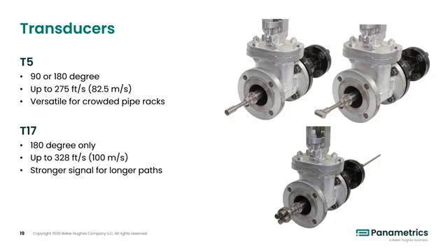These are the black bell-shaped objects you can see on the backside of each isolation valve. These are recommended for lower pressure applications that are under 80 psi or 5.5 bar. These have a PTFE packing gland, which allows for the transducers to be retracted and the isolation valves shut without opening the line to atmosphere.